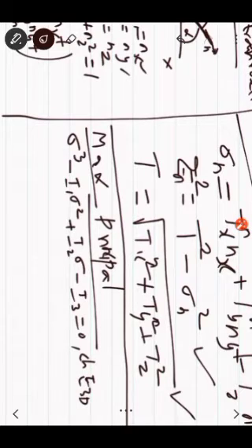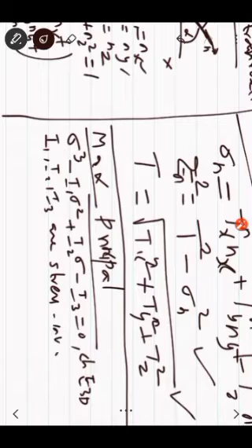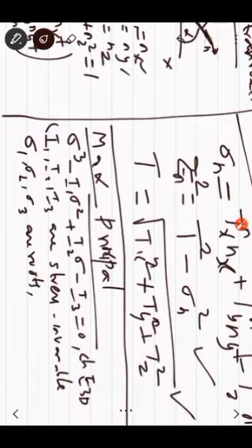Here I1, I2, I3 are stress invariants, which will not vary for the same given state of stress. If I substitute these values there, I will find the roots sigma 1, sigma 2, sigma 3. Here sigma 1 will be maximum, sigma 3 will be minimum, and sigma 2 will be intermediate.